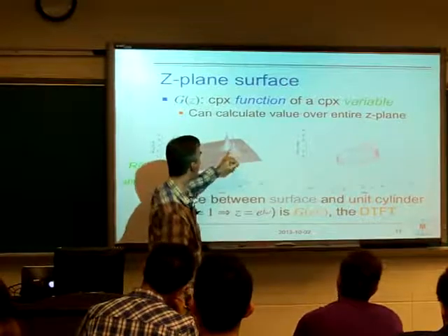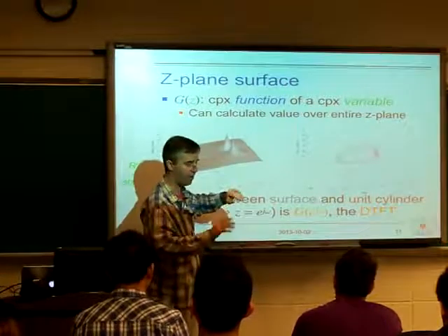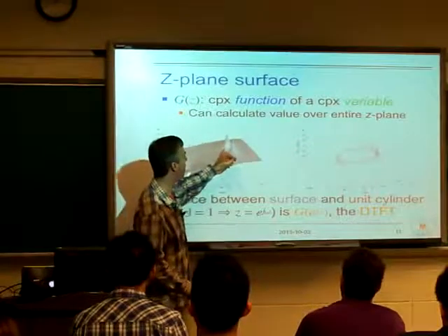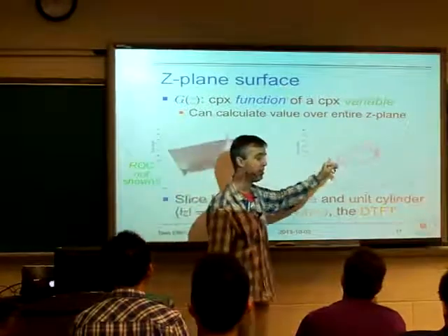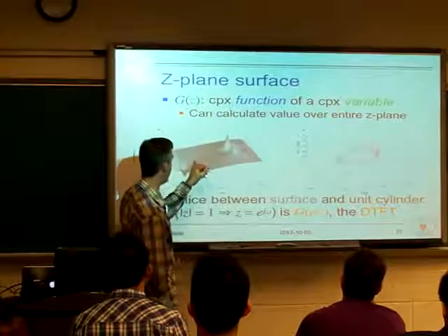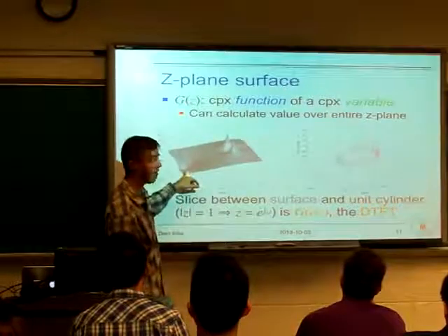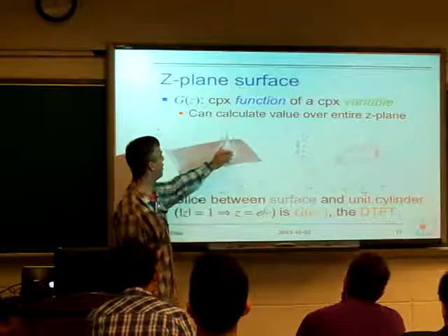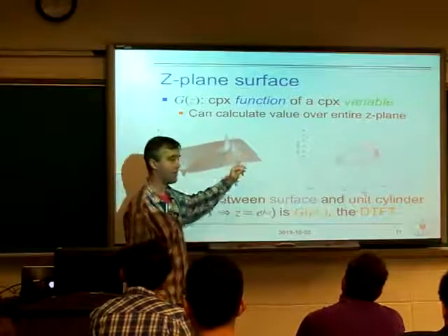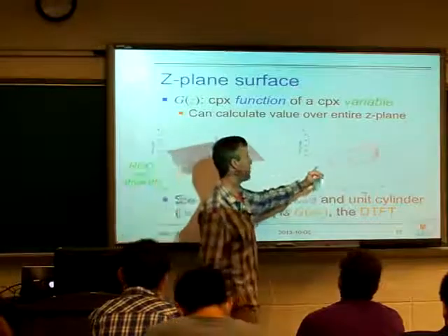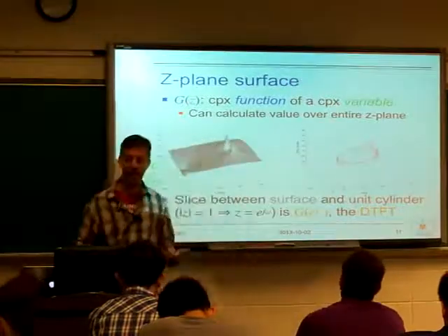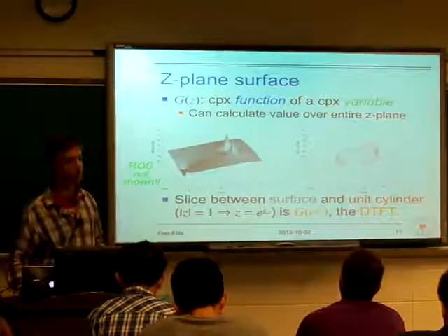And so now, this is the whole payoff. Knowing where the poles are, and knowing where they are in relation to the unit circle, the poles and the zeros, right? This dip here is because we're approaching this zero down here. We know where the poles and zeros are. We can guess how they're going to interact with the unit circle. That will then tell us what the Fourier transform is going to look like. And then we quickly get an insight or a rough idea about what the system is going to do.